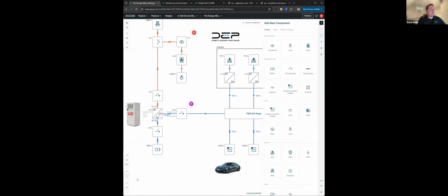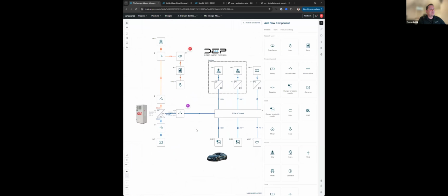But if you look at this DC microgrid design that we put together, the fault current sources, even though there's a battery attached here, go through a power conversion unit. And even though there is solar here, it goes through another power conversion unit. What that means is that your fault currents are limited here. So you really want to make sure that when you select your electromechanical circuit breakers or solid state breakers, you have enough fault current capacity to trip them, once you filter them down and make your selection.